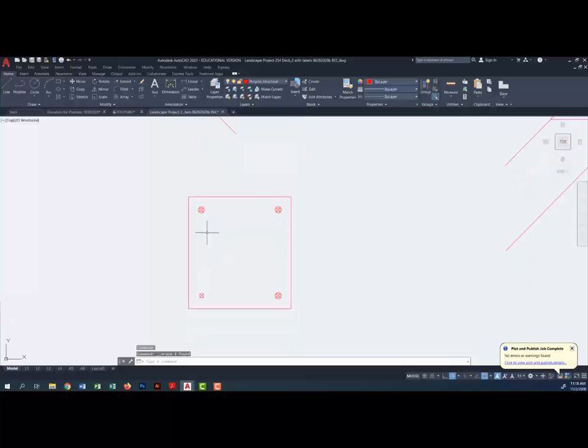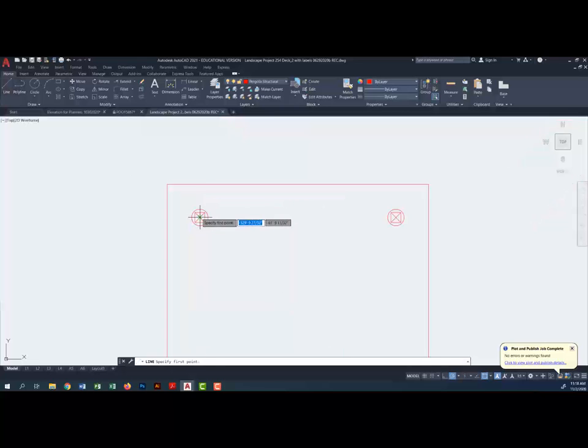Now I'm going to draw the actual lintels first, and the lintels will go in the horizontal position. So I'll draw a line, and I'll bring it right to the outer edge because it goes the full length of the 2-foot offset. And I'll extend this line to there. And each framing member is 1.5 inches. So I'll offset that by 1.5, or another 2 by 6, 8, 10, or 12.